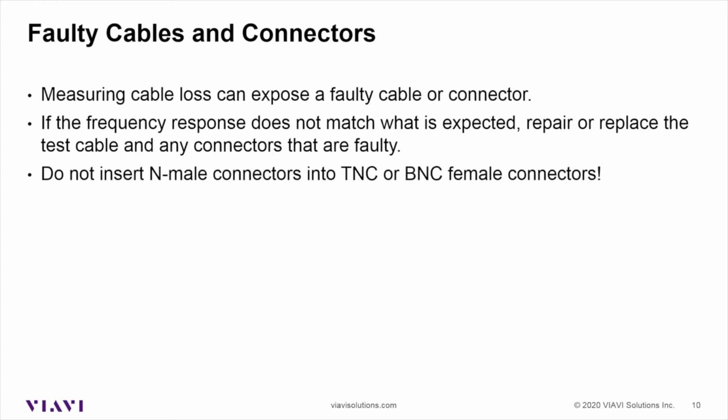One of the things I've run into is people, when they're doing a lot of testing and they've got their N connector on their cable, of course they've got a BNC or TNC adapter, or usually a BNC adapter, on their radio, and they don't want to take the time to go find the right adapter to hook that N connector on to that BNC connector, and they'll just take that N connector and shove it in there. And that will work for a while.